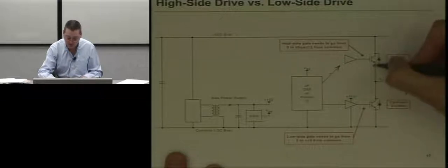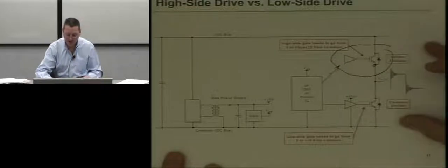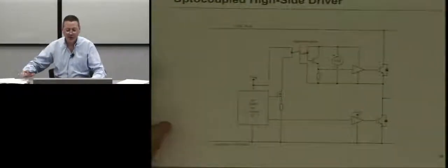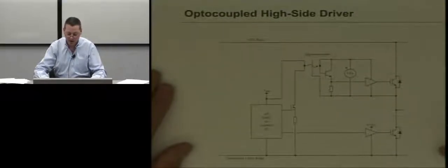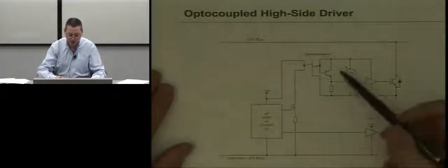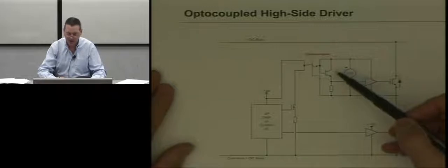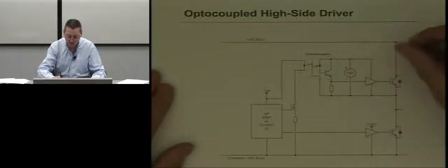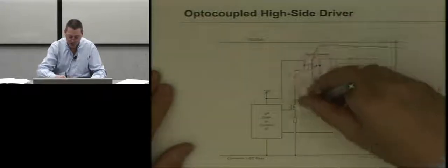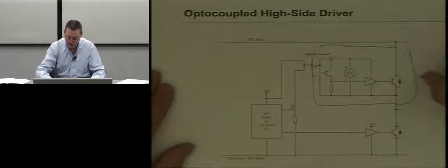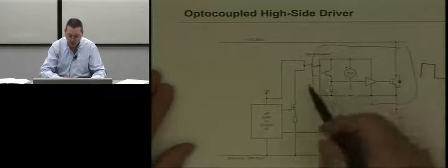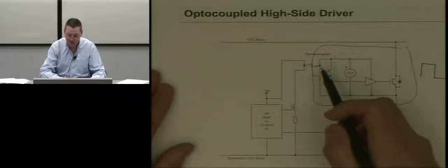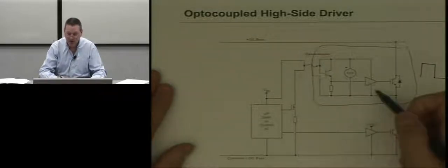that's basically the emitter here. So is the gate, right? This whole thing is moving up and down. So one way to do that is to isolate, using some sort of optocoupler, which is commonly used. So that allows this whole node to float up and down as you switch the output, and you communicate with light, essentially photons, to tell this when to turn on and off.